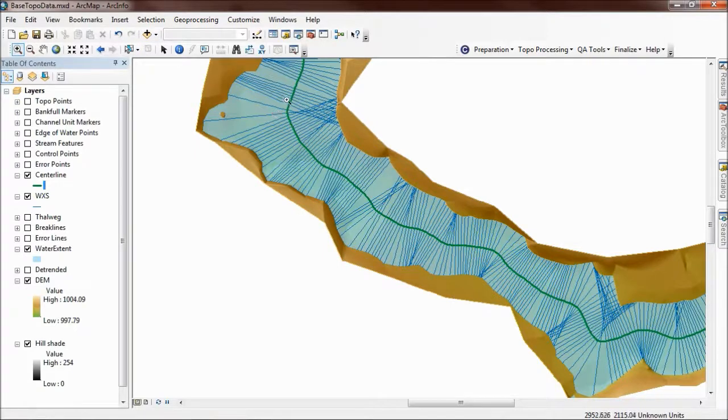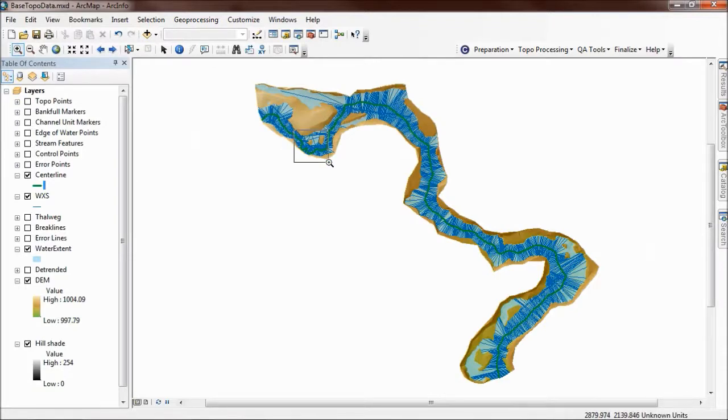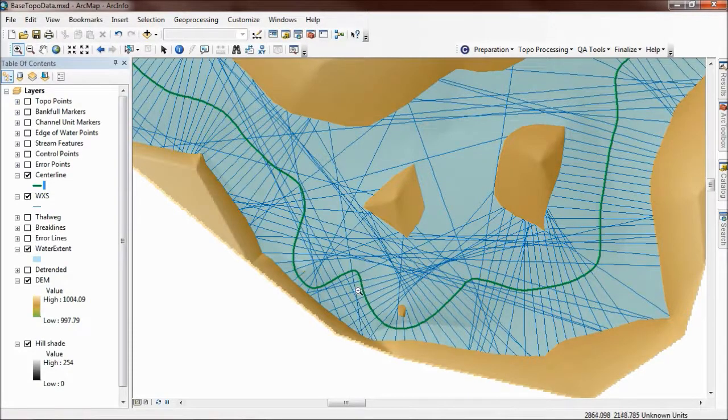So turning on the cross sections option does take longer, but it does actually help you identify certain issues with your centerline. So up here we have this issue, and you'll see that going around these islands has created quite a mess of our cross sections. So what I would do in this situation is go into an edit session and manually edit the vertices of this centerline to have it run just manually down through this section. Again, you want quite a smooth centerline because you don't want the cross sections to deviate too wildly.